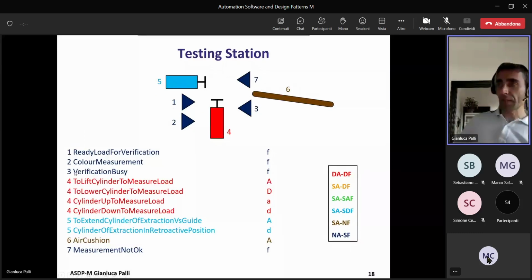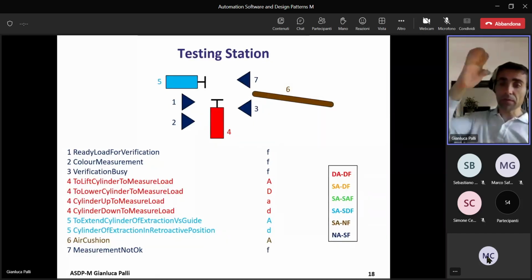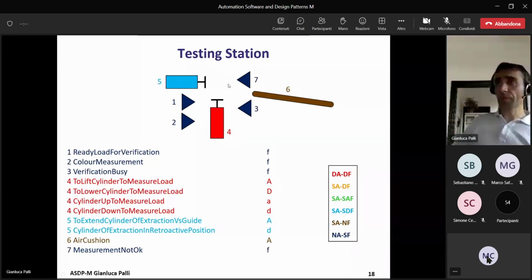This is a photocell that detects that the arm has already moved out of the space of motion of the ejection cylinder. You can skip it by using the 2 sensors detecting the position of the lever arm, or eventually you can use it to detect that the arm has already passed out of the motion of the elevator.